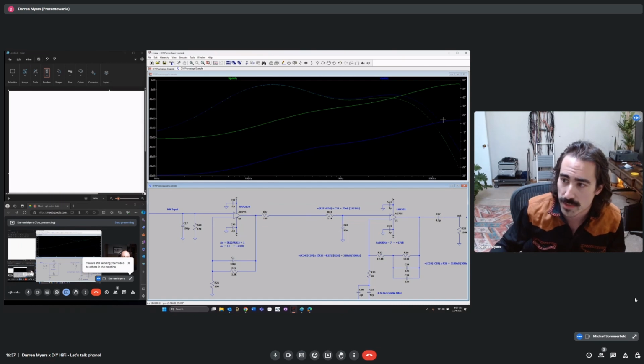You're going to actually clip the high frequencies because we're so boosted. If I were to apply 40 dB in this stage, it's going to cause an issue where the high frequencies clip before the low frequencies. And that is not desirable.